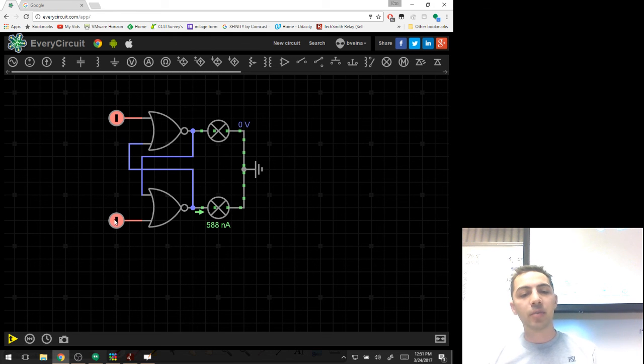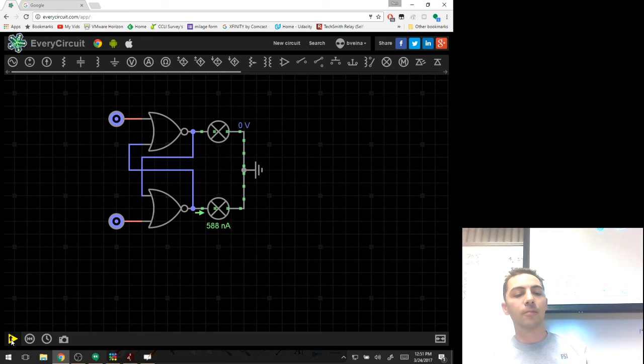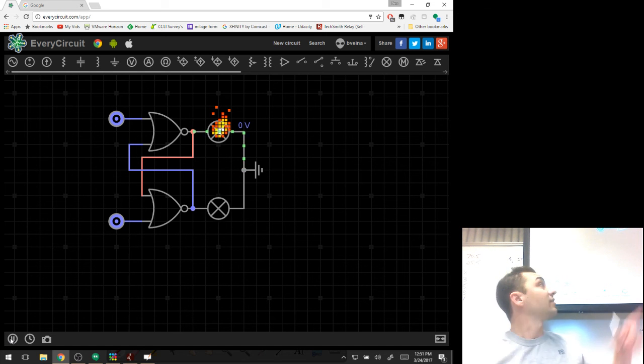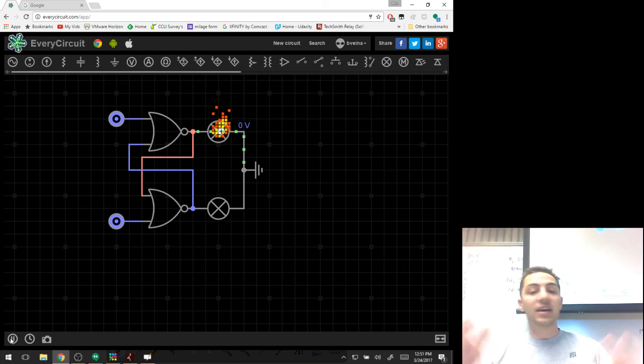What I'm going to do is pause this simulation. I'm going to see if I can make this work. It might not. I'm going to set them both to 0 at the same time. Now I'm back to an astable configuration. For a second, it did eventually, yeah, good, excellent. I'm glad that did occur. It does eventually figure itself out because there's a certain propagation delay in these, and it's not going to be exactly matched. So eventually, 1 will take over.